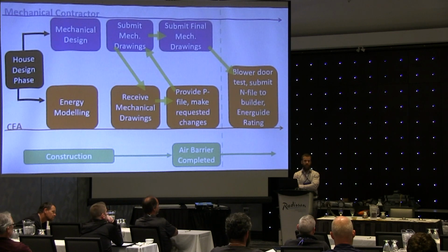It's an awesome point. Yeah. If I come out with a heat loss of 25,000 BTUs, I probably don't want to install a 28,000 BTU furnace. Cutting it a little close, right?